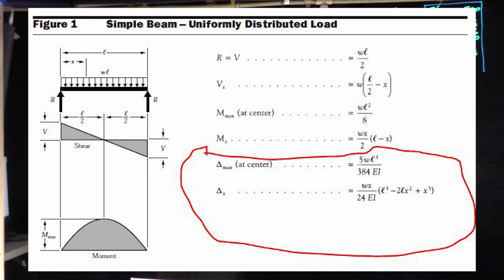Okay, so the deflection is, we know the equation from the beam formula. Delta is equal, actually you can go to section 5.4, hold on, let me write this down. 5WL to the power 4 divided by 384 E prime IX.